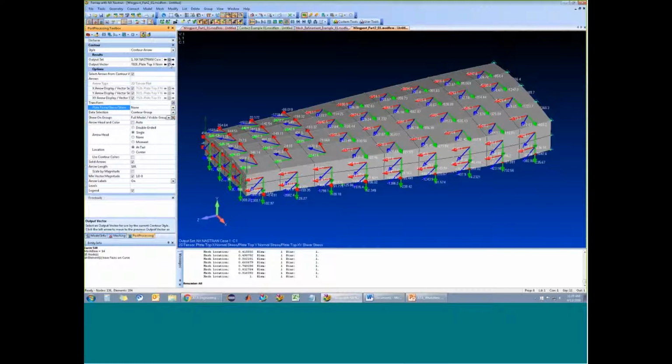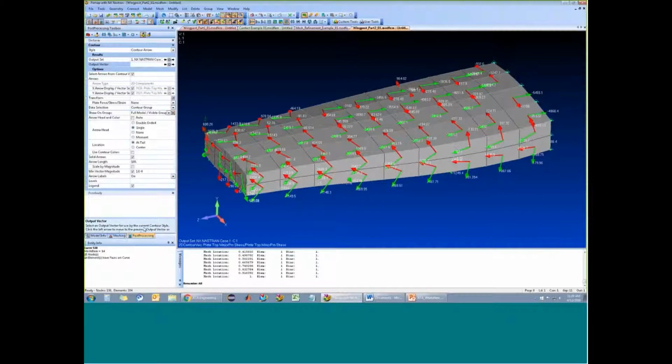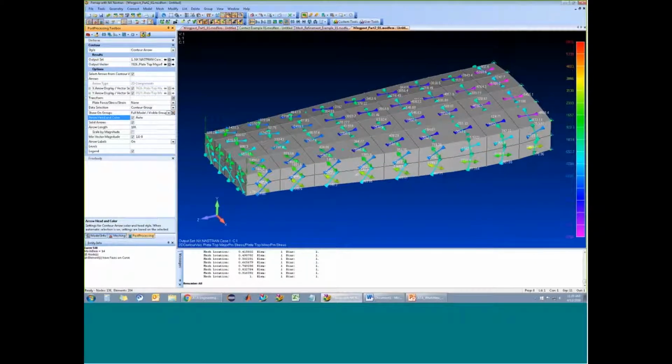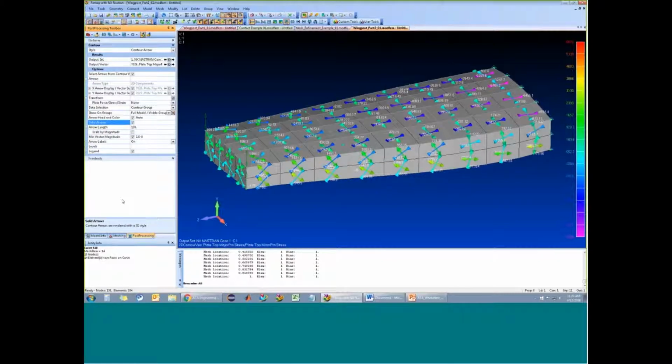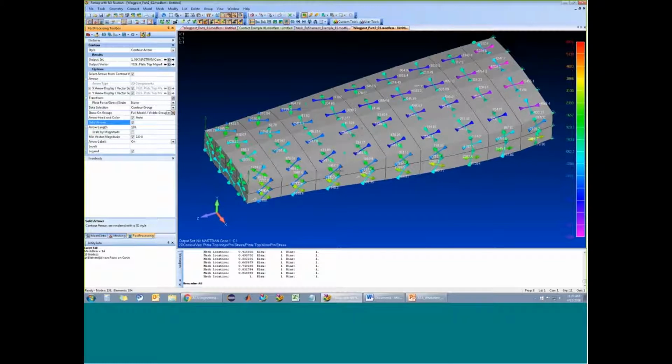We can also choose something like principal stresses. And if you turn back on auto, because we made some changes, then it'll auto update all of your settings. So now we're seeing compression, tension arrows. You could make them solid or not. Again, you have a lot of options here to make things look exactly the way you want them. And with the principal stresses, you can see they automatically showed up at the correct angles as well for each element.